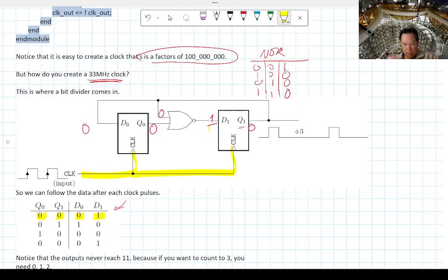All right, so let's say this is a positive edge, so when the clock goes up, right, what's going to happen is that the data from D gets sent to Q, right? Since in this case, right, D0 is 0, Q basically gets changed to 0, right? Let's just write that, right, comma 0. Okay, so well, that didn't do anything, but right, D1 gets sent to Q1, so therefore this actually changed to 1. Okay, now this feeds back up to here, right, where it just switches this to 1 and